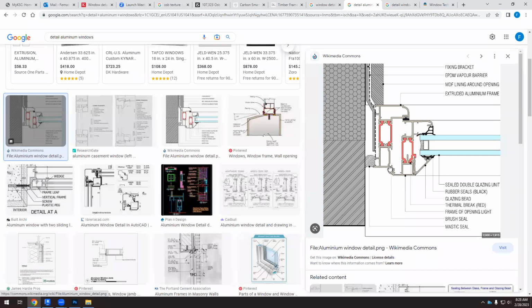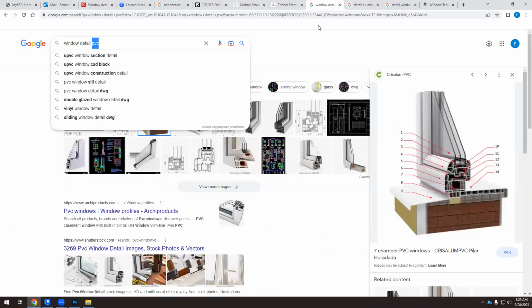Okay, so it's aluminum outdoors, it's aluminum indoors. We love aluminum; it's a nice material, but we have to interrupt it in the middle of the frame, between the fixed part of the frame and the movable part of the frame here. Okay, so it's quite complicated. We don't have to design it. There are engineers designing frames to make them more effective. But when it comes to the PVC, we don't have to interrupt the material because PVC is a plastic, a thermal insulating material. So we don't have the same issues that we have with aluminum, but we have to create more cavities to prevent heat from entering the building.